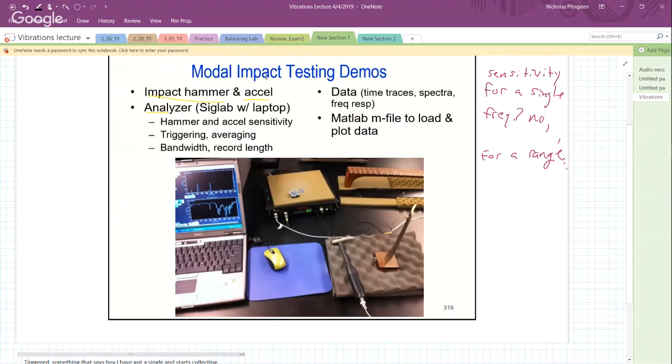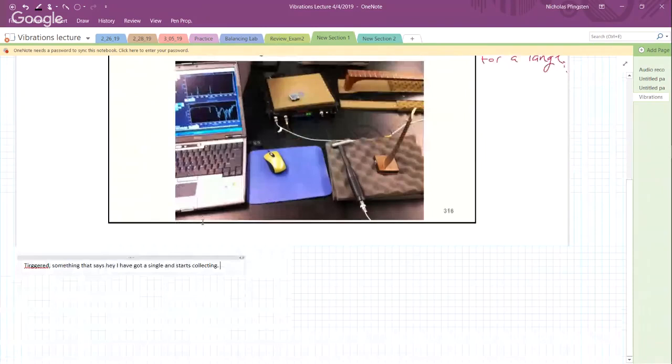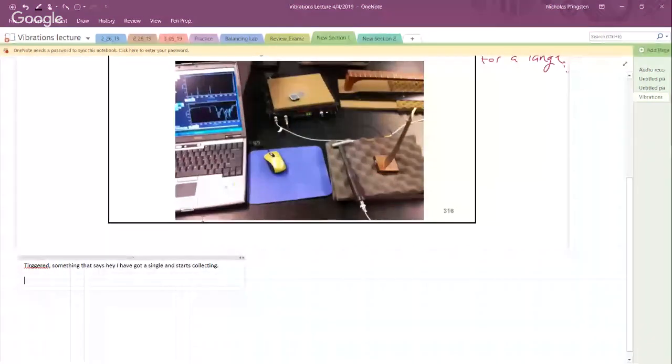All right, so that's what it is. We'll look for a change in voltage. When it sees that on channel 1, it's going to start grabbing data. In fact, I tell it, hey, not only grab that data, grab some data before that. It's called pre-trigger.